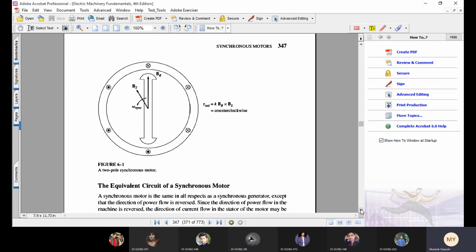For example, you press the button, the capacitor is installed, it gives the single-phase machine an initial torque, and the machine starts rotating. Now if you remove the capacitor, it will keep rotating. But right at the initial time t equals 0 plus instant, we need that capacitor to be installed there. Okay, so this is the case.